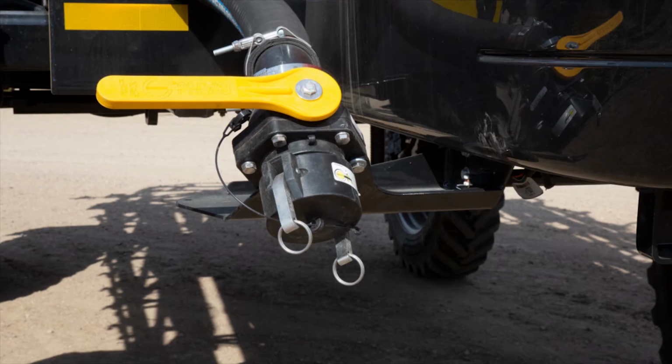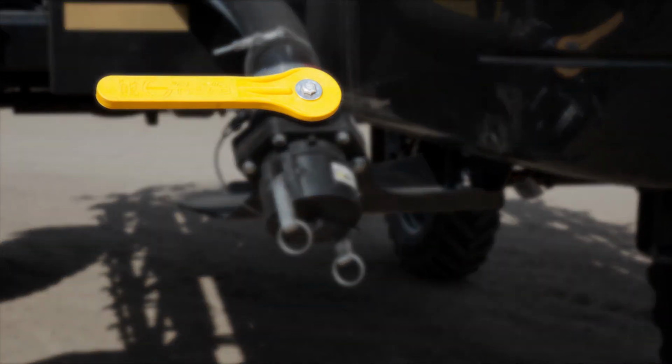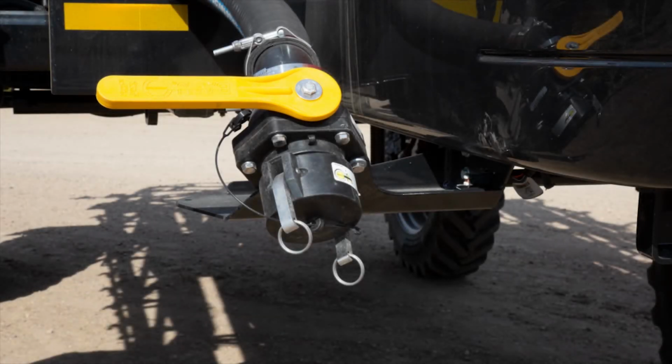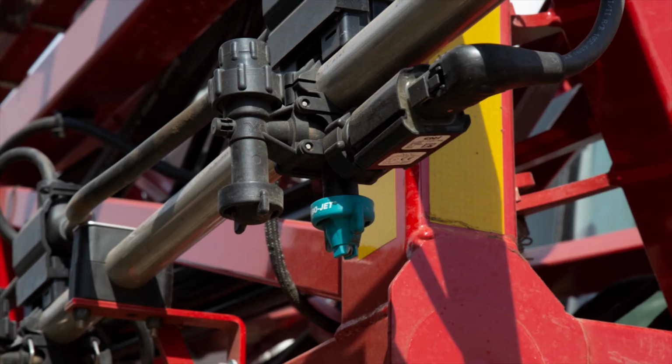If we look at the Case machine, the 4440, here's our front fill option. That's a 3-inch line. Again, very similar to what the Deere has. One difference here is the lack of an air purge option available on this particular machine. If we look out in the boom of this Case 4440, one thing that's very prevalent out in the market on a lot of these machines is AIM Command or AIM Command Flex in this case. This is a system actually manufactured by Raven, very similar, with a few different changes, to their Hawkeye system. Now we'll talk in some comparisons between John Deere's pulsing solution, specifically in comparison with the Raven or with the AIM Command Flex in this case.